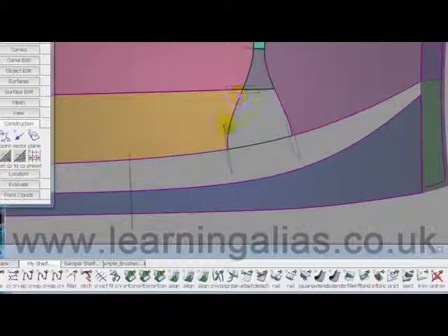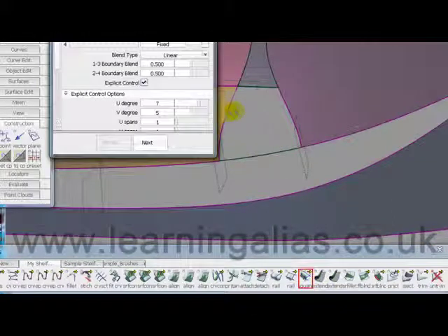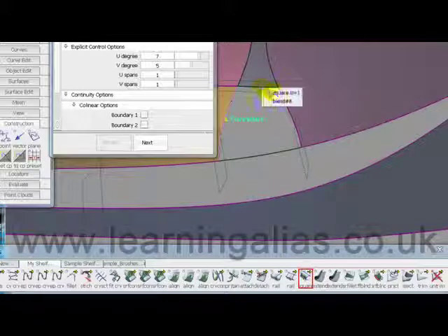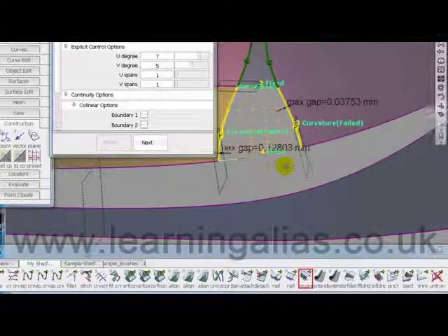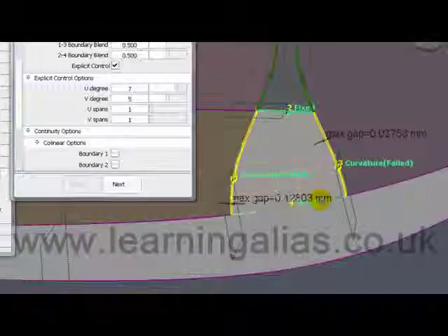This is the shape trimmed out, given to us by the tubular offset control. So I could have actually put in a constraint here and another constraint there with the tool, the manipulator, to get a different shape here, because I know from experience that this kind of bell shape is not going to be conducive to building a good surface. We'll put a surface in there so I can show you what the problem is likely to be. So I'm going to make sure that I haven't got my collinearity on here, and just pick there, pick the square, not the curve, and controls on. So it's built a square, but we've got a gap here, quite a big gap actually, and we've got a small gap there.